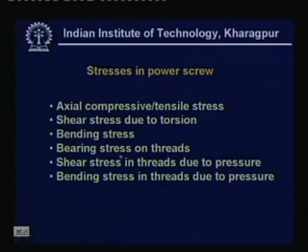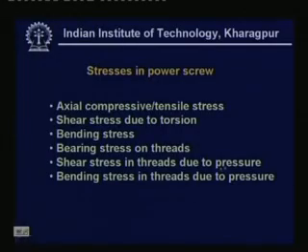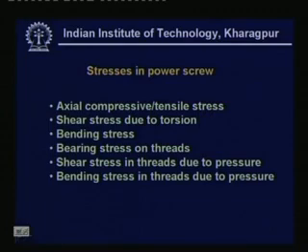Then comes the bearing stress on threads. This is very important. Most of the power screws fail by this bearing stress, and if the bearing stress becomes very large, then lots of wear and tear goes on, and that has to be prevented. So, this bearing stress is very important and has to be taken care of. Then the shear stress in threads due to pressure. You have seen that the shear stress developed in the threads is because of the pressure. Then the bending stress in threads due to pressure.